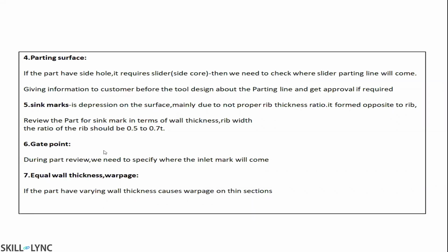Then the gating point, we need to clarify from the customer where we need to place the gate. Why is the gating point important? If you place the gate point on the top surface and it is a visible component, right? So always place the gate in the non-aesthetic region. And equal wall thickness and warpage.